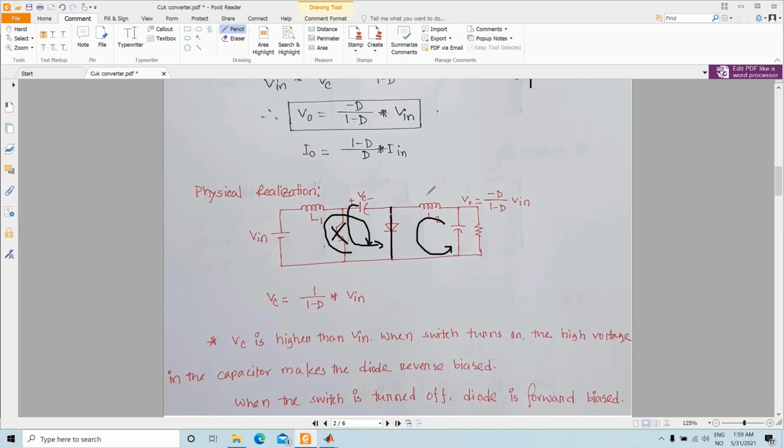This inductor current is the same as the capacitor current for the time when this capacitor and inductor are connected. That means in the second phase, this IL2 is the same as the capacitor current, and you can consequently derive. Once you get this inductor current, the AC part of the inductor current will flow through the filter capacitor, and the DC part will flow through the load.